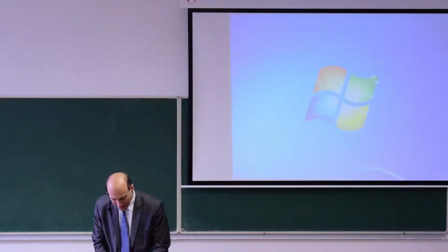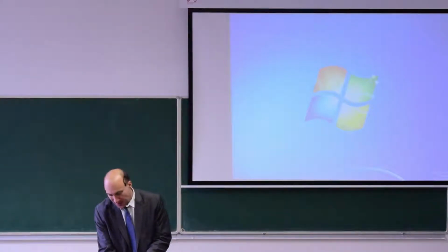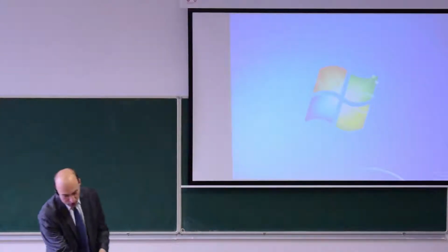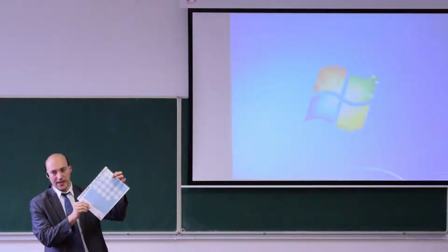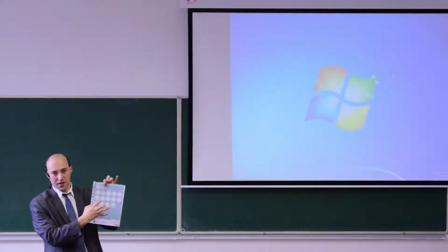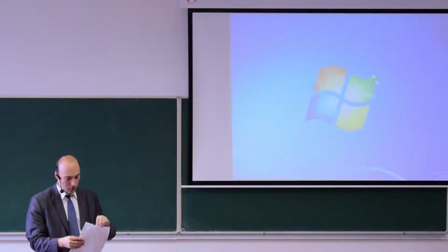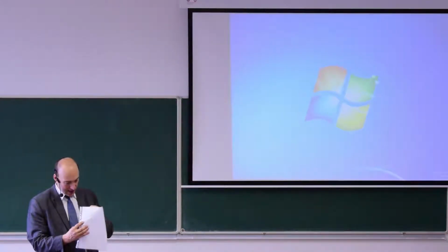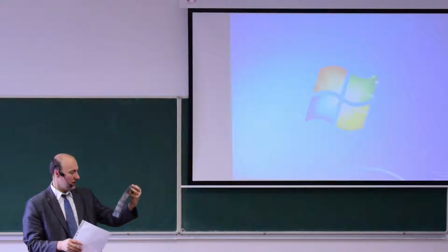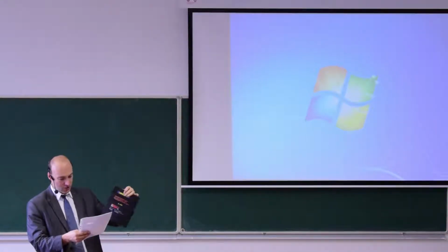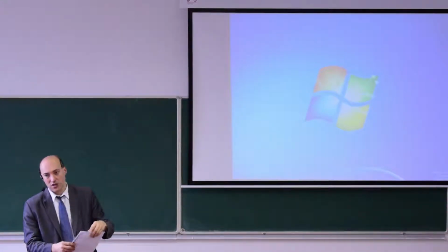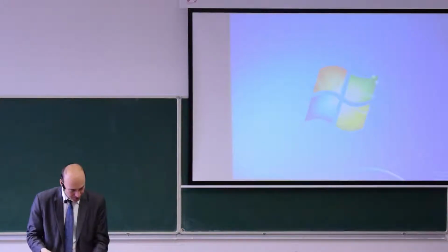How can we work with that? We can use those stickers that have a defined emissivity. That's one option. Those stickers work up to relatively high temperatures. I think they work up to something like 200 or 300 centigrade. So this is one option.